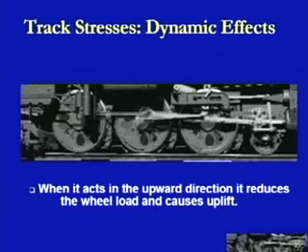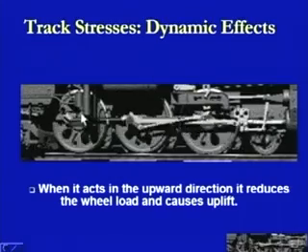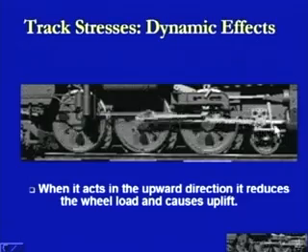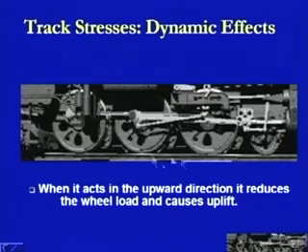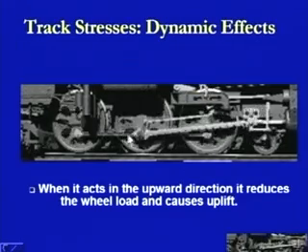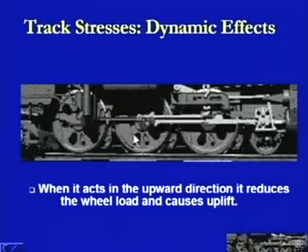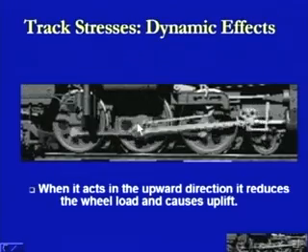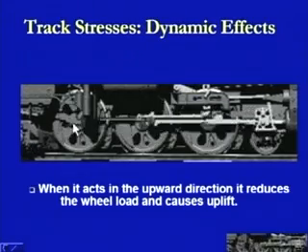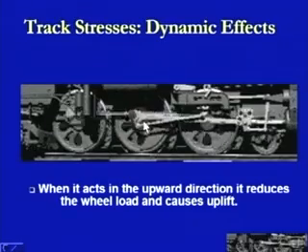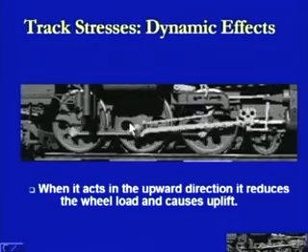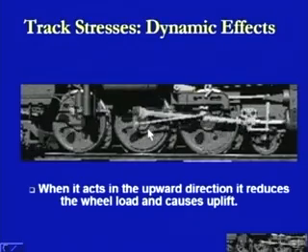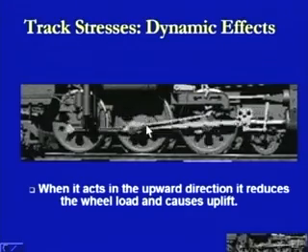Here we can see in this diagram the moving parts. This is the center of the wheel, and this is the piston on the side, and this is moving with this one. The cranks are being provided, and the loads provided at these are revolving around the center of the wheel. Therefore, there is certain eccentricity being induced at this point here, and similarly at this location here. Because of this eccentricity, there are certain loads attached at the other side, so that it gets balanced out, and this is how it works.